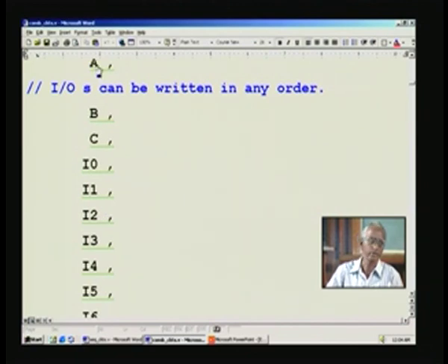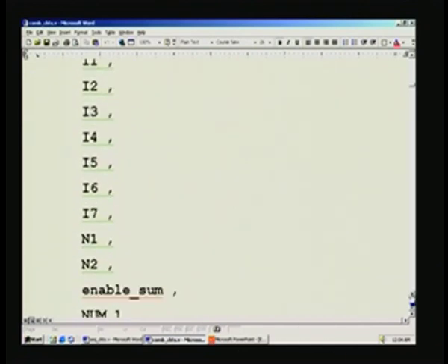And another thing, I wonder whether I mentioned it to you earlier, why is this style adopted? I will explain. This again depends upon the designer. I prefer this style, and the reason is we can easily spot where a particular signal has been used or not used by mistake. So, if you club all of them in a single line, which you can do, it will be difficult to track. Of course, there are such features in editors, but this will be an easier thing. So, I leave it to your taste to handle it. There is no restriction regarding that.